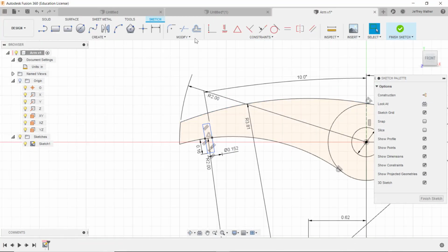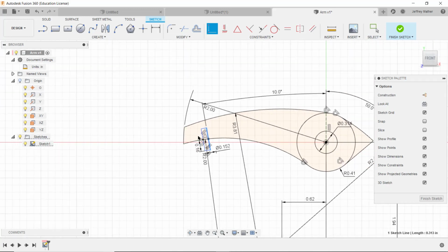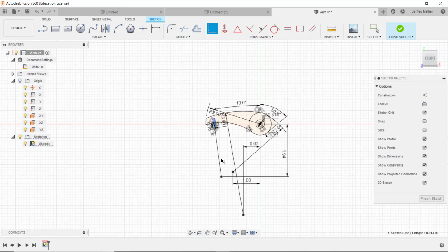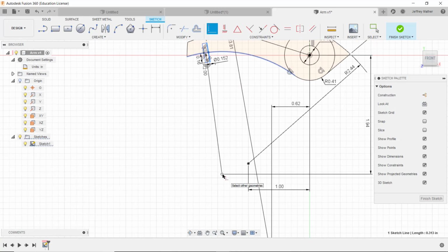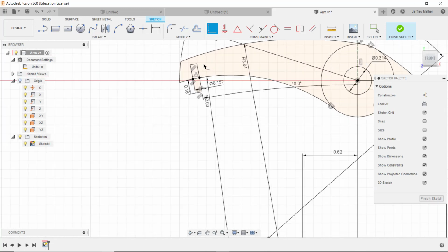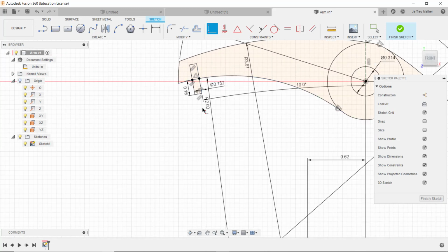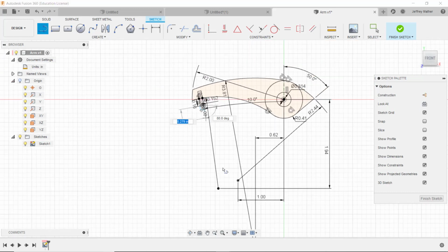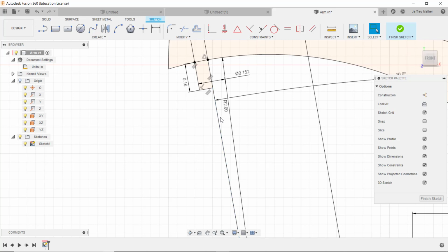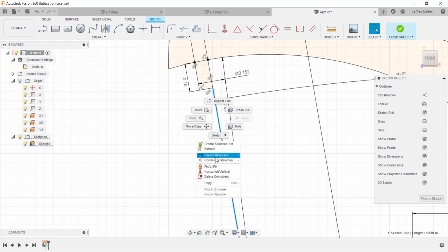And anyway, so I'll do coincident. I want this line, the center of this pin, to be coincident with the center of this 2-inch radius arc. And when I do, if you drew an imaginary line, sometimes it's a good idea to put in these construction lines so that a year from now, I'll change that to a construction line.